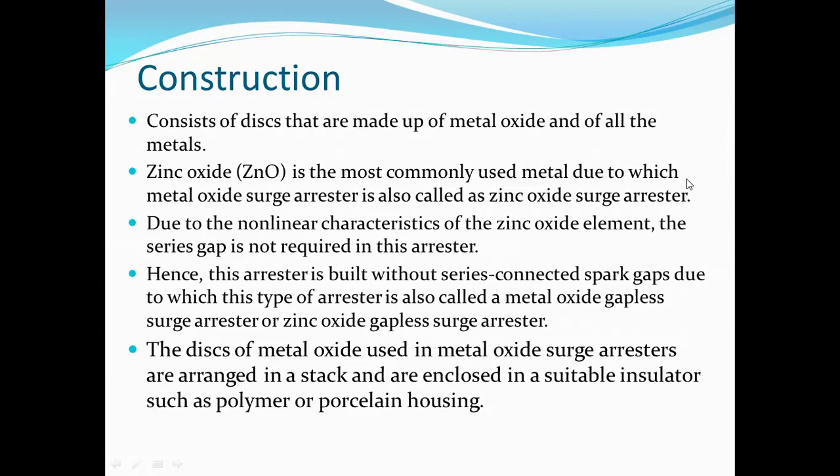The discs of metal oxide used in the metal oxide surge arrestors are arranged in a stack and are enclosed in a suitable insulator such as polymer or porcelain housing.